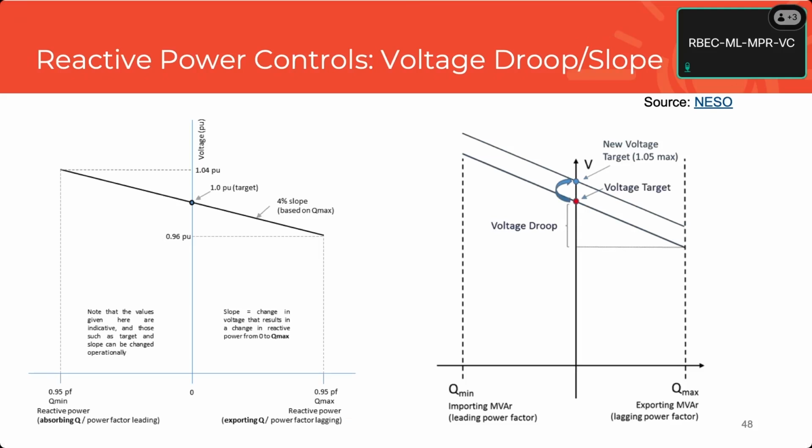Okay, so very, very sensitive reactive power. As soon as the voltage goes up, you're going to slam against that, and as soon as the voltage goes down, you're going to slam against the other rail. So the voltage controller is very sensitive. You can add a deadband if you want, and that's fine. Now that will work, okay? So possibly it will work, but it basically will be just a very, very sensitive controller.